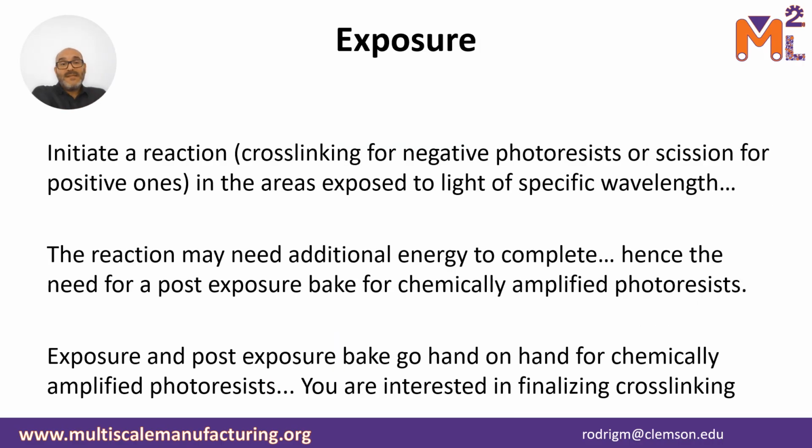What is the goal of exposure? That will be to initiate a reaction, right? A cross-linking for a negative photoresist or scission for positive photoresist in the areas that are exposed to light of a specific wavelength. For SU8, usually we use 365 nanometers.